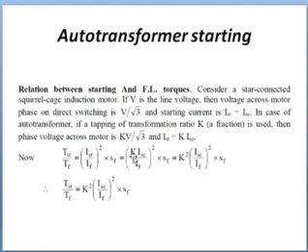The rotor circuit short circuit current is k times that of DOL starting. So the torque is reduced by k square times, and the starting current is also reduced by k square times, because when we consider starting current, that is the supply current. So using the transformer principle, the starting current will be k square times that of the primary of DOL starting.